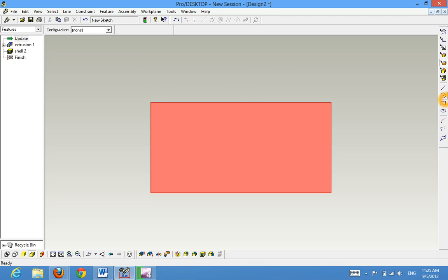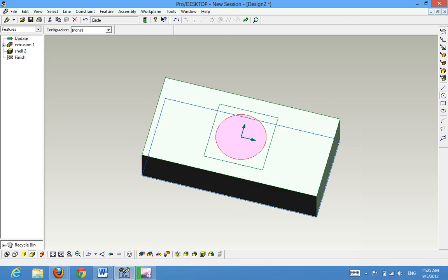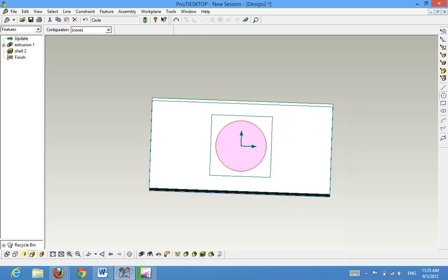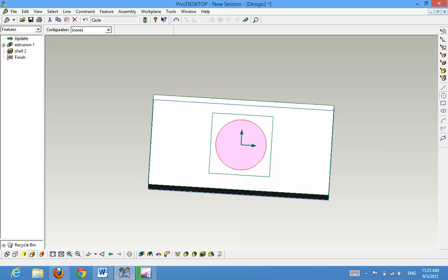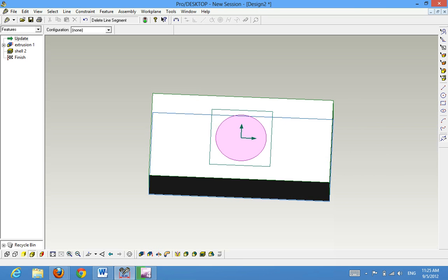For this exercise, I'm going to keep this really simple. I'm just going to make a round sound hole of 84 millimeters. Okay, so there it is. It's a valid profile. I know it's valid because my shape is shaded. If I have one stray line somewhere on that sketch like that, all of a sudden it's not valid, and I will get an error when I try to extrude it. Now in the next video I've made, I've done it with a complex error, and I've shown how I've unraveled that error basically. Anyway, here we go. So I've now got my valid profile.